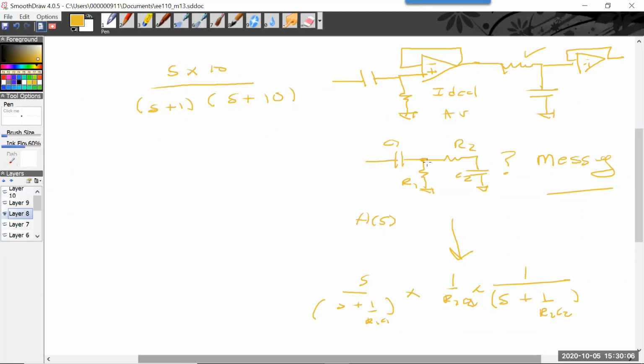No, this is a linear time invariant system, just like this is a linear time invariant system. It just makes it so that I can take this transfer function and multiply it by this transfer function. But if I were to analyze this circuit, let's just try to calculate a discharge time from here. Well, the current can go that way, right? But it's got to go through this R2, but then that's being split from here and here. So this RC is affecting this RC.